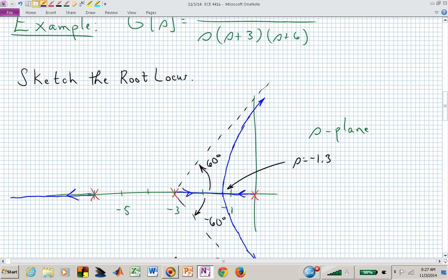So we could find via an inverse tangent the y where that asymptote crosses the imaginary axis. And so pay attention. On some exams, I might ask you, where do the asymptotes cross the imaginary axis? Don't spend all your time trying to find where the root locus crosses. The asymptotes, where do they cross? That might be an easier question. Is that clear?